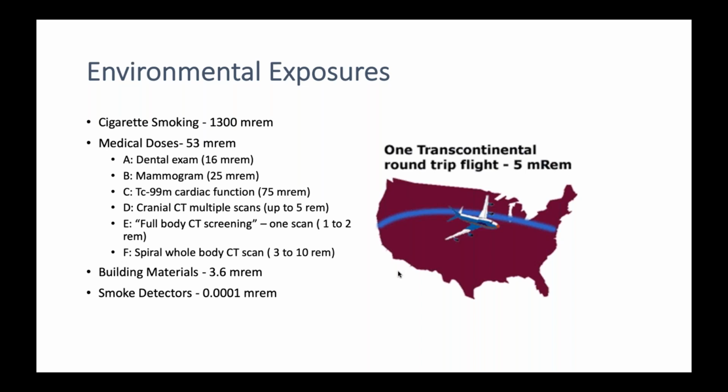Right? So you can keep the area outside of the foundation under a negative pressure, so we won't get stuff from the house. You do the same thing. You just put a sensor, tent it over the soil, dig a little hole, tent a dry area, put it in there, leave it for a few days, and then have it analyzed.